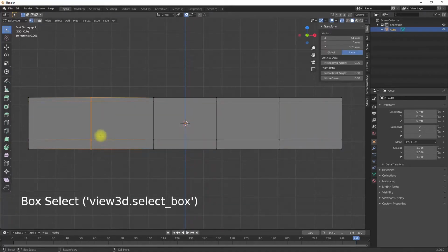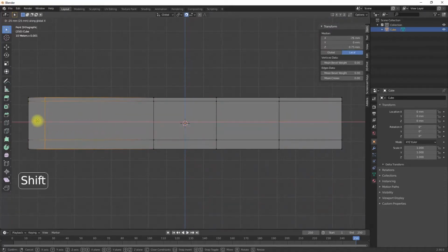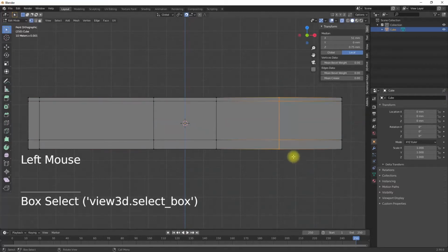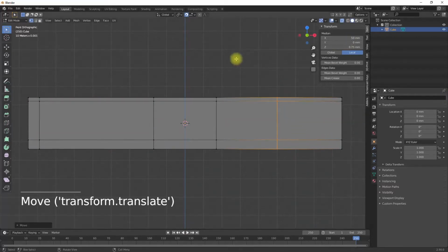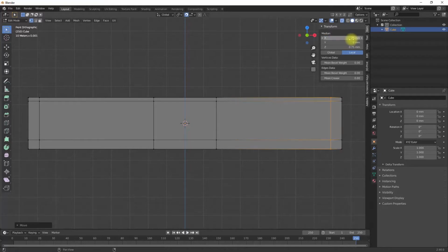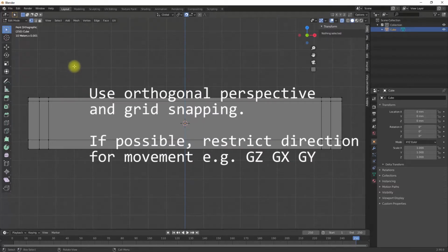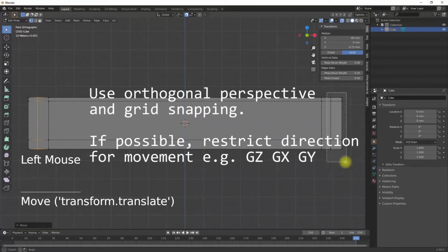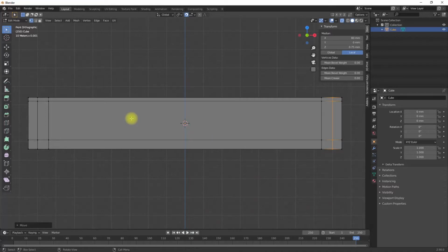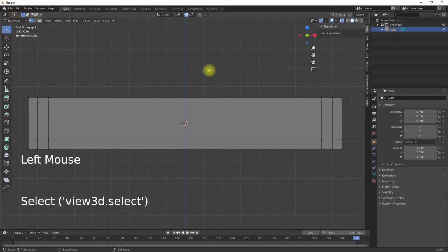Therefore we can use the loop cut tool to slice and dice or project into the necessary topology that we use for modeling later on. Switch on absolute grid snapping and go into the orthogonal view. Now you can move your loop cuts very precisely and use the grid for snapping.